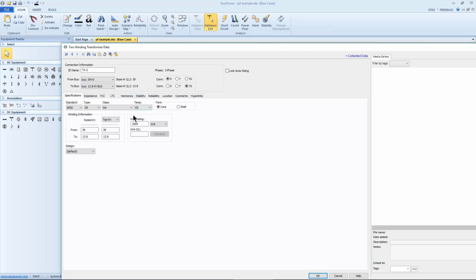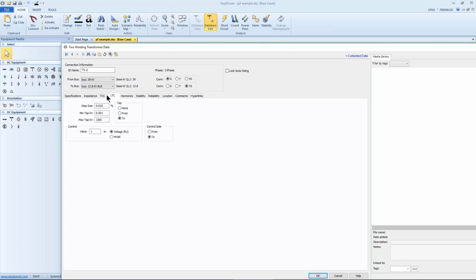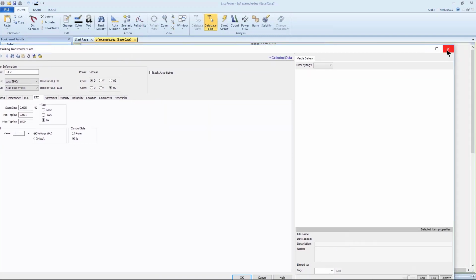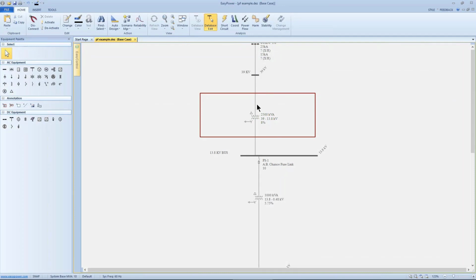My suggestion was that the PowerFlow tool has the ability in a transformer to set up a load tap changer. In this case, we're going to have this main transformer set up with a load tap changer that regulates on the 2 side and will change the taps on the 2 side based upon whatever the optimum power flow solution will be. So this is the way we set up our base case, and so we set it up as a load tap changer.